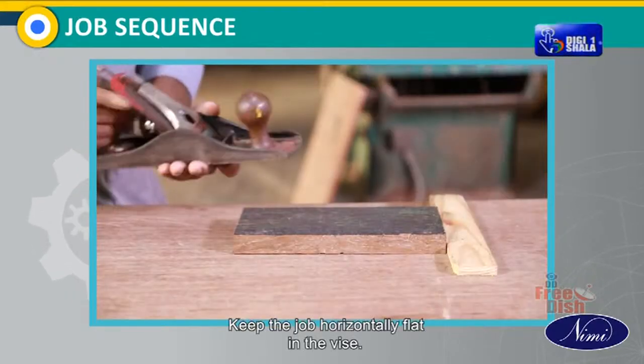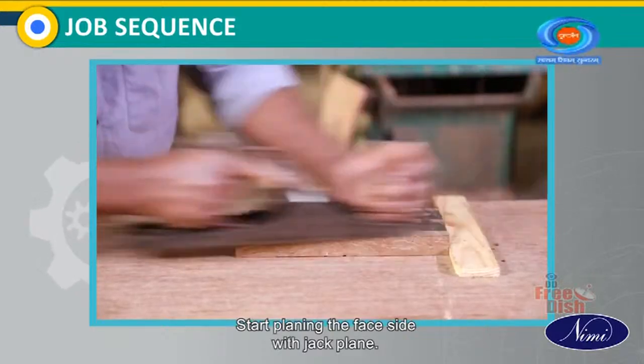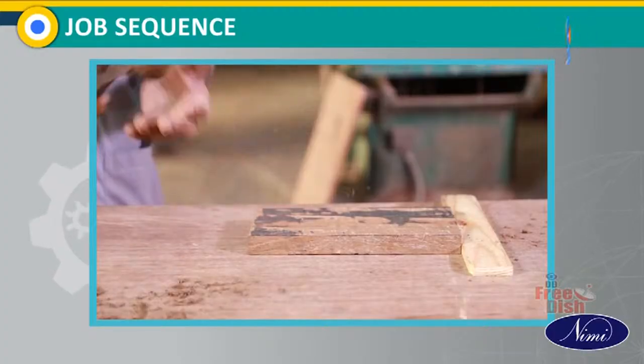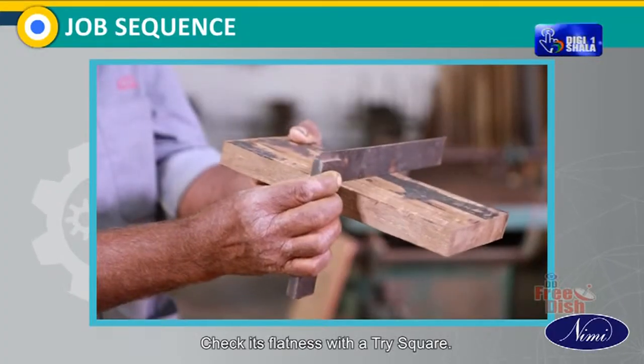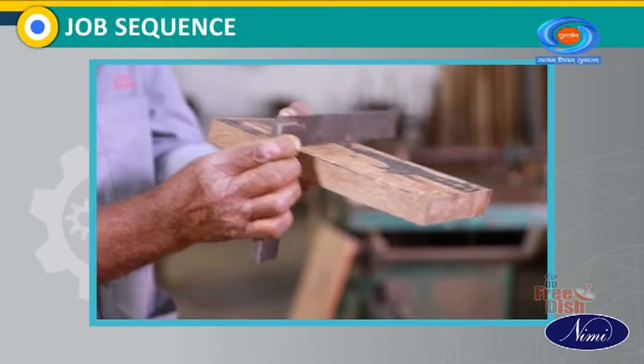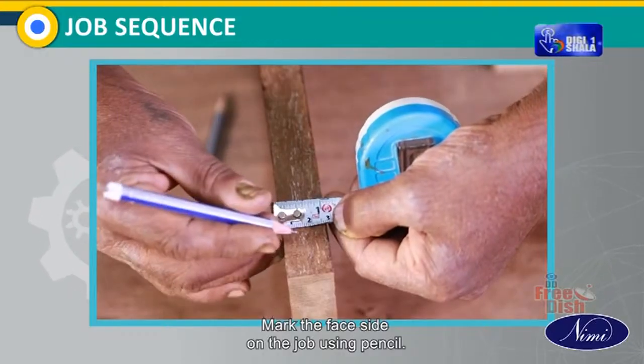Keep the job horizontally flat in the vise. Start planing the face side with jack plane. Check its flatness with a tri-square. Mark the face side on the job using pencil.